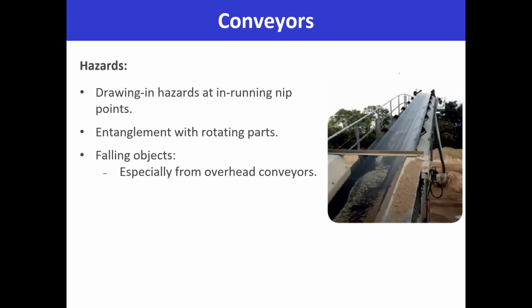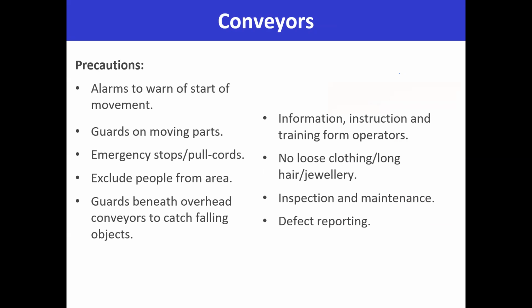Okay, then there are conveyors. Conveyors have their own hazards such as drawing in, and nip points are there where they can draw you in, entanglement with rotating parts, and falling objects such as from an overhead conveyor.